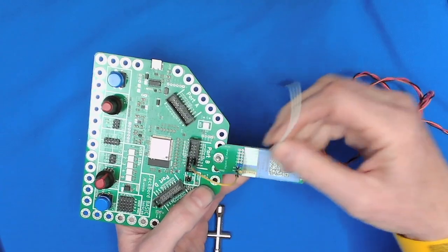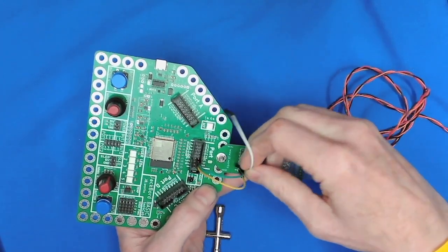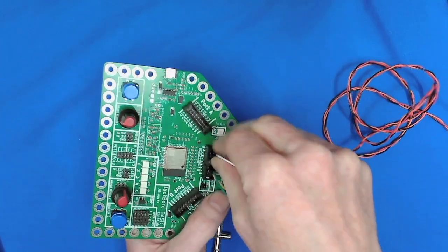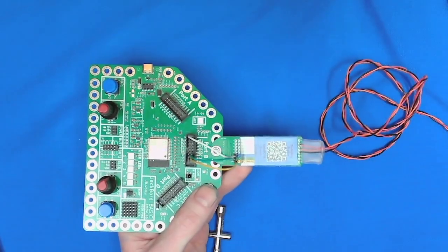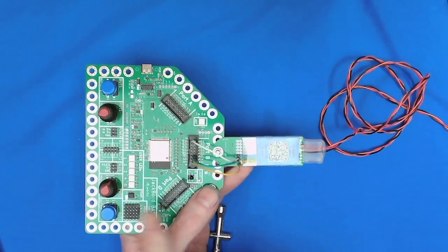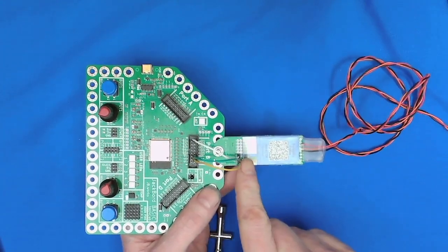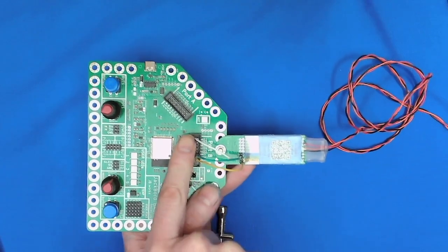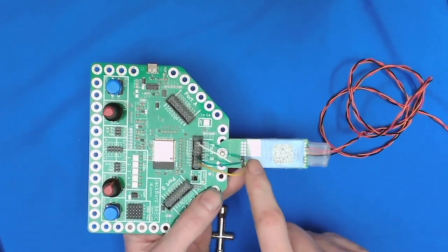And then finally we need to get the voltage output from the sensor into the JackBord. So we're going to go from the blue pin on the sensor to port pin B1. And that's our connection. So essentially we have 3 volts power going from port B over to the sensor, ground going to the sensor, and then finally port pin B1 going to the voltage out pin on the sensor.